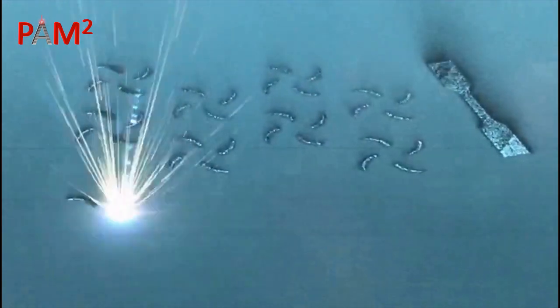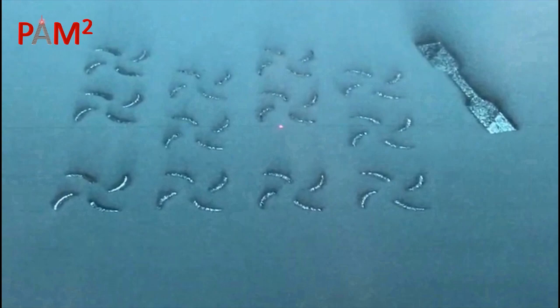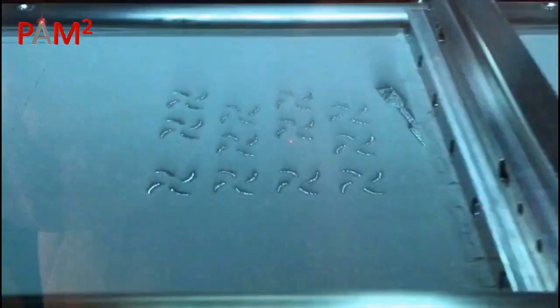Many physical phenomena occur during the laser powder interaction. We use the laser beam as the heat source to melt the metal powder, but a large amount of applied energy is reflected by the powder. The absorptivity for metals is usually between 0.2 and 0.8, which means 20 to 80% of the energy delivered is absorbed, depending on the metal.